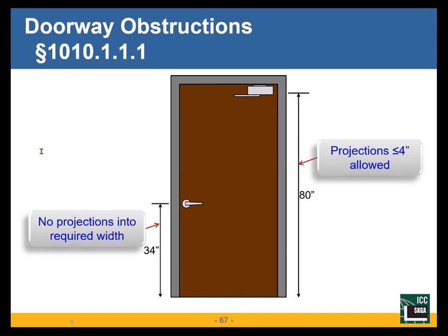Does the occupant load for large restrooms get included as part of the total occupant load? It depends how you're doing this. If you do it the way I suggested, take the whole floor area and divide it by the occupant load factor, yeah, I'm going to include it. If you get down to the gross versus net issue, in a gross area calculation, it's included. I would just use the same occupant load factor that I'm using for the rest of the floor.